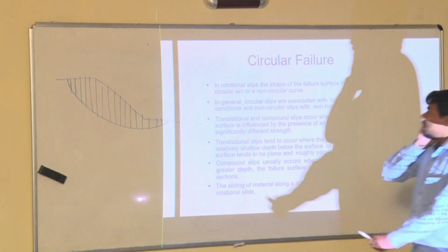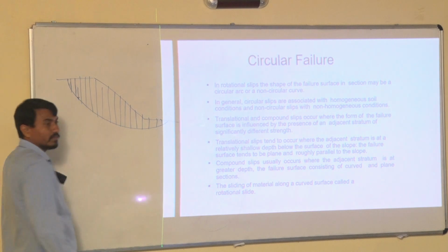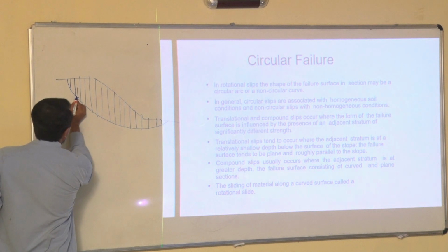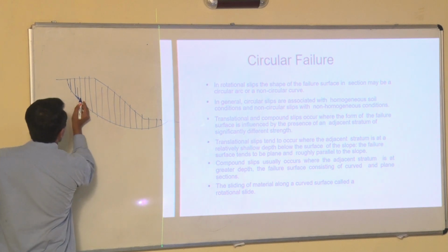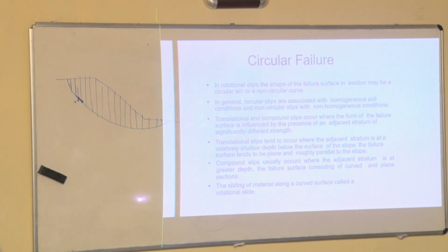So this slice basically indicates there is a weight, there will be some self weight of the mass. So if it is an inclined surface, self weight will be divided, one perpendicular to the plane, another along the plane. So for every slice, this kind of vector is possible, two types of force vector are possible.